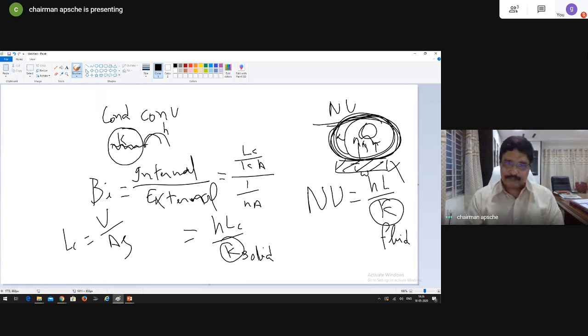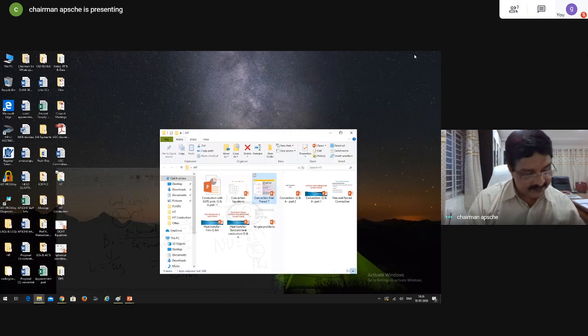Okay, so absolutely you cannot compare between them. Biot number, we use it in transient heat conduction. It compares solid resistance versus convection resistance outside. Whereas in Nusselt's number, we are comparing the resistances offered by the same fluid. For air, the convection resistance of air and the conduction resistance of air. And that's how you take the thermal conductivity of the fluid. Hope I've explained it sufficiently.